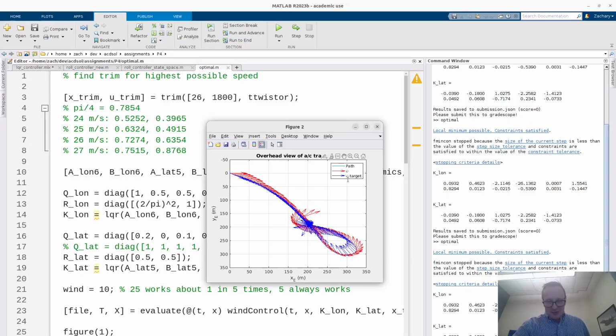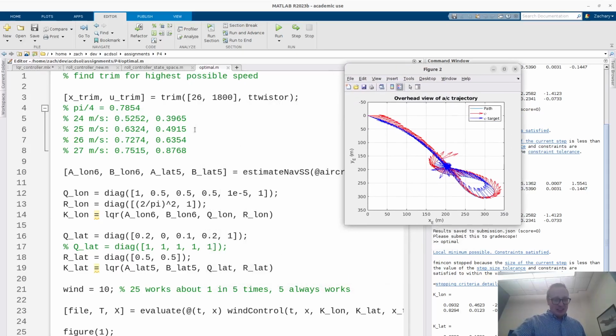And so I calculated a psi target, which is denoted by these blues. And then I had my LQR controller, and the true psi, the heading angle, is denoted by these red things. My LQR controller tried to follow that, and you can see it actually, even after it hits the goal, tries to come back around and fly this way. So LQR is a very robust and easy way to calculate those controls. It only took a few lines.